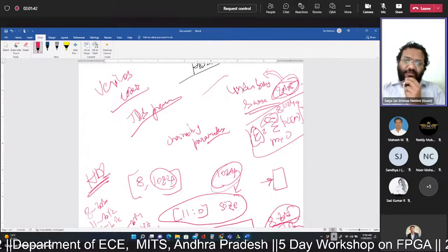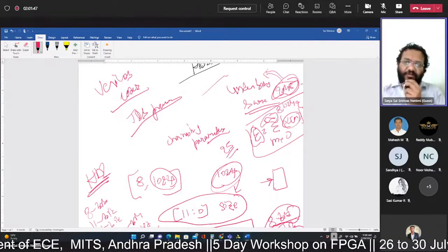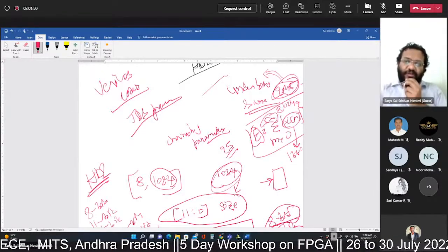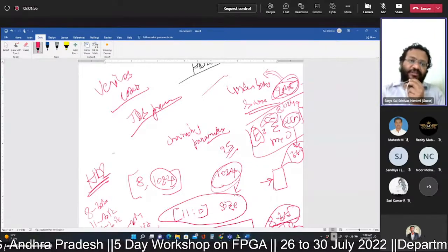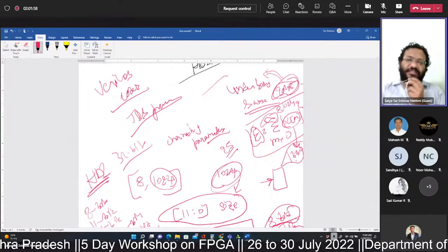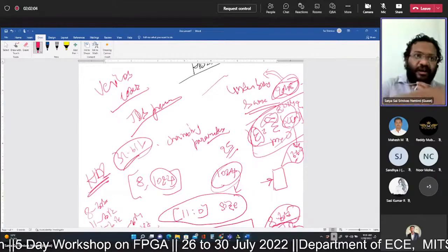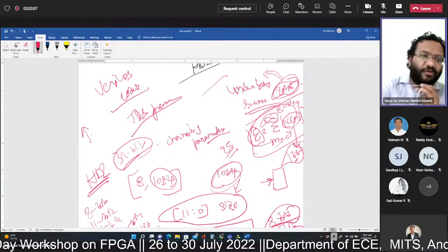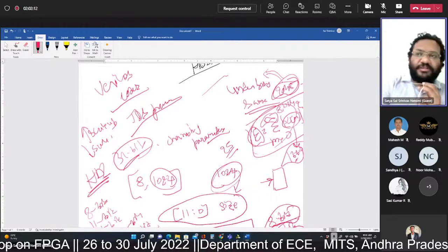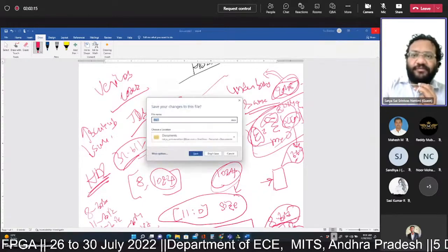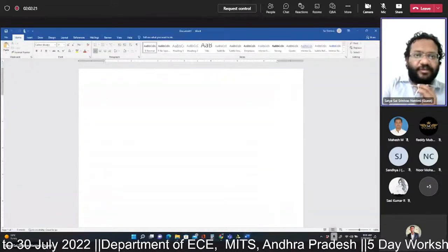Again, this energy value we have represented with 25 bits, and this x of m value we represented with 16 bits. Now if I change the input signal, if I say it is not 16 bit but 32 bit, only the representation is changing, but the underlying concept remains the same. When this representation changes, ultimately your hardware will either scale up or scale down. So what is meant by scale up or scale down?